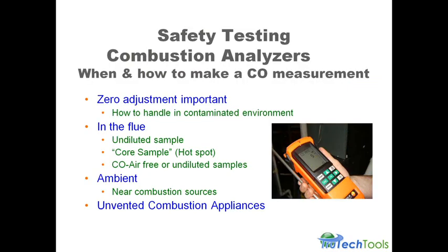All right, safety testing. So how are we going to do this? Well, most important thing, zero the analyzer in a non-contaminated environment. Typically that means you're getting out into fresh air. We're going to zero that thing in fresh air. It's going to go through a countdown, and then we're going to be able to do our testing. So we're going to zero it, test the air.